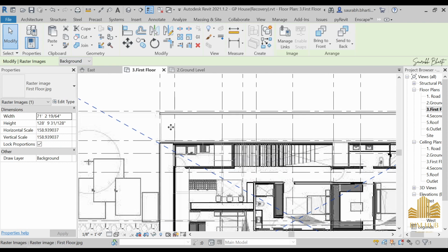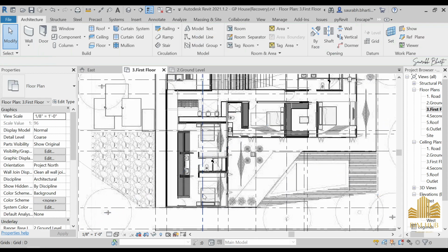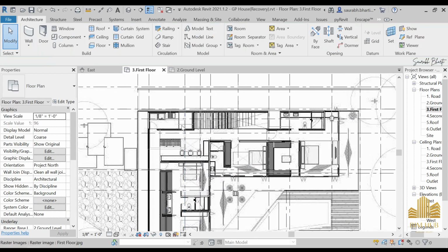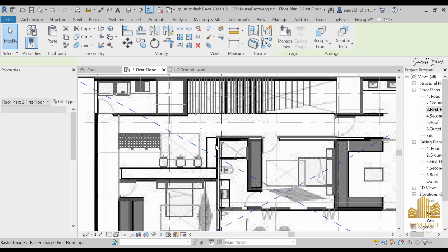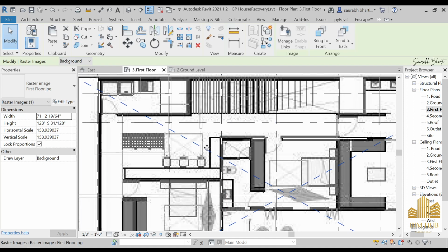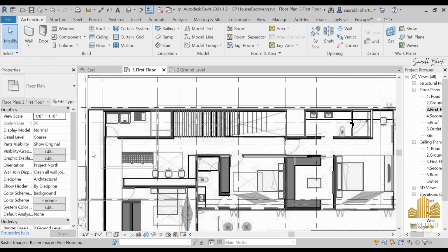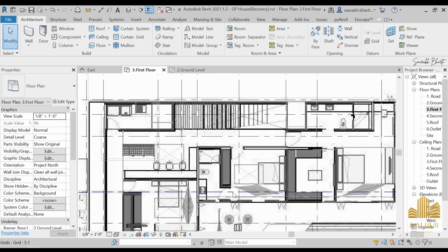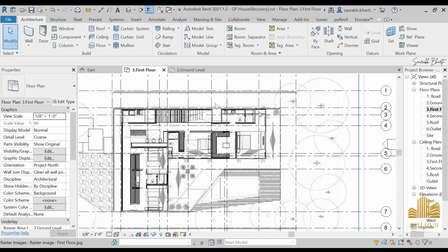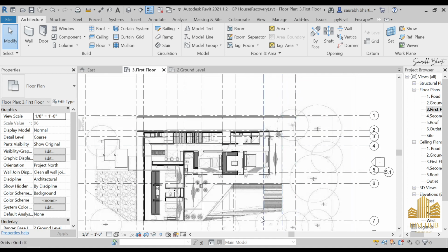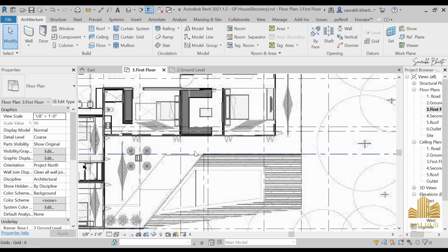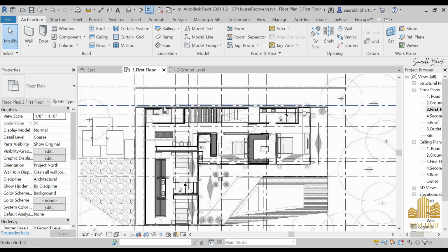Okay, this is our louver, this is our grid, and also remember to check your grid lines, and the most important part of it. So from grid lines, as you can see, this is not matching, so we have to match it. And now from here I can see that this place is matching, this place is matching, this place does match with our wall. Here we have our wall and it does match, and this doesn't match, so we can keep it like this, not a problem.